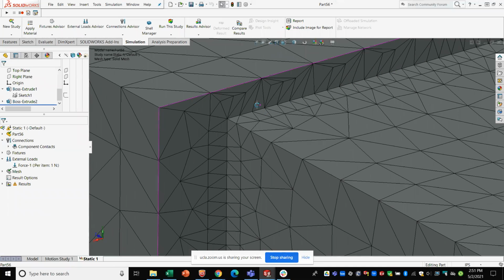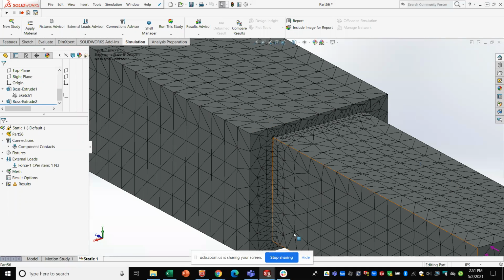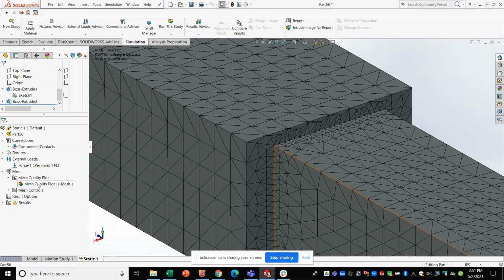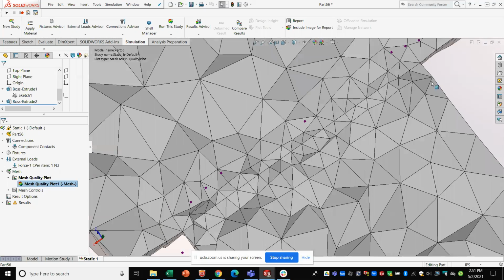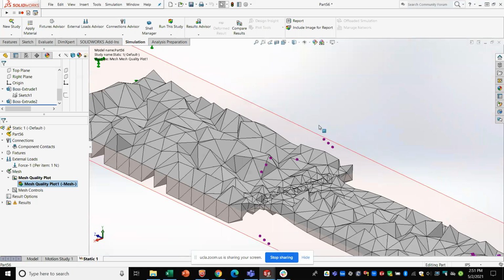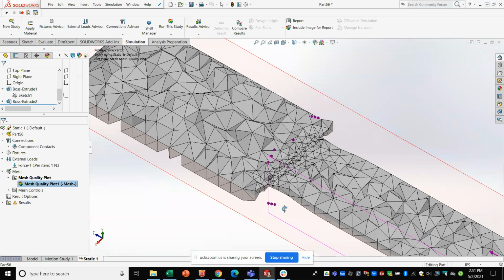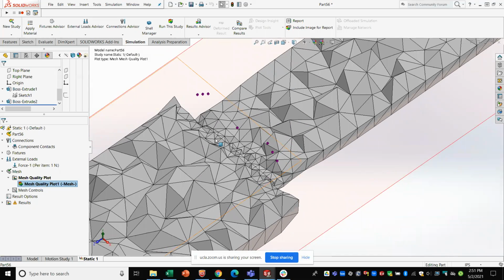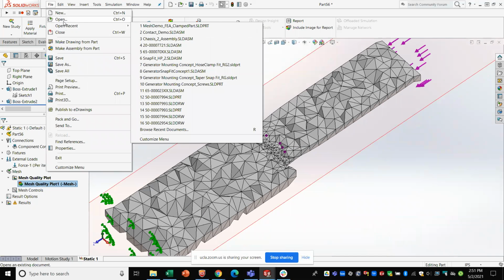See, now with the compatible mesh option selected, what it does is it traces the outline of the smaller face onto the larger face. And it, again, forces them to share nodes and elements across that boundary. And so this is useful where you're trying to simulate a part that you want to behave as a single solid part. So I'll get into that. Actually, let's open another one.